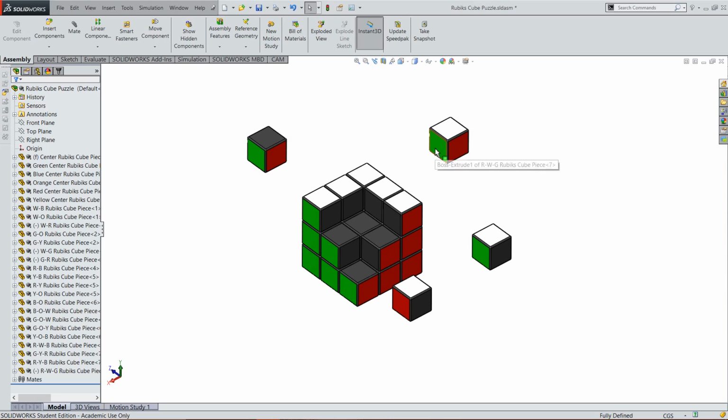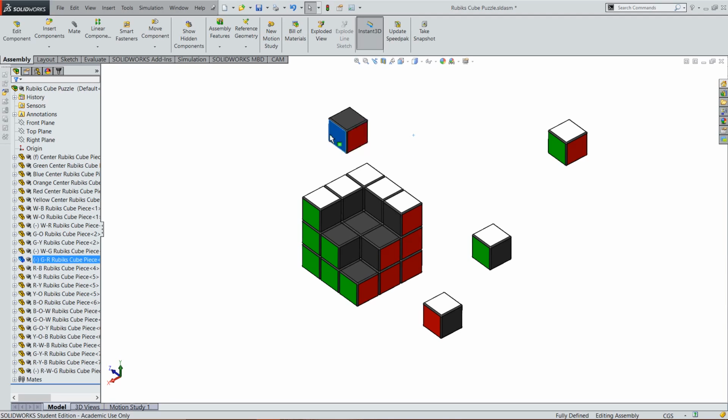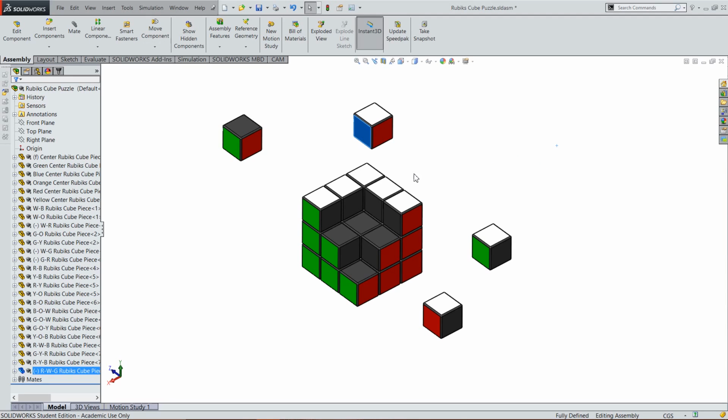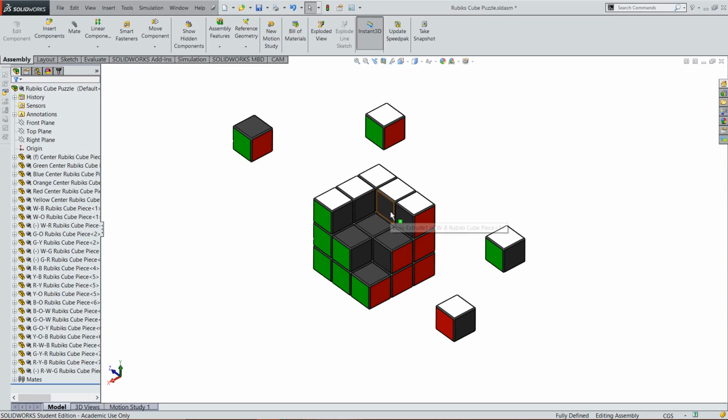And you can move objects inside assemblies simply by clicking them and dragging. Click and drag. And when they highlight like that, that means that I've selected a surface. And you can deselect by pressing the background. Alright, so get used to navigating around in SolidWorks because you really want to get the fundamentals down with this before you start designing stuff.